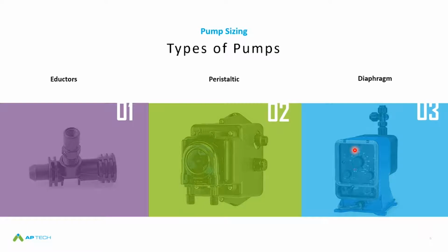where you have a mechanical room located in the basement and you have a 400-foot tall building that has a cooling tower on top. Well, that's a lot of gravity or head on those water lines in the basement. So you need a lot of pressure to overcome in order to inject your chemistry. So that's why diaphragm pumps are pretty favorable on that.